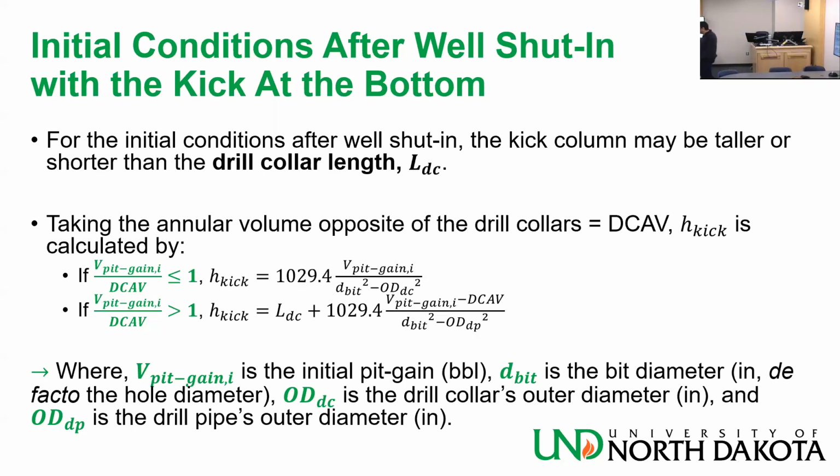The BHA in real life is much more complicated than a set of drill collars of fixed outer diameter. Sometimes it takes a whole tower, a whole shift, 12.5 hours to make the BHA. And then it has to go up the rig floor with a forklift and be run in. The BHA is very, very important. It's the most expensive part of the drill string.